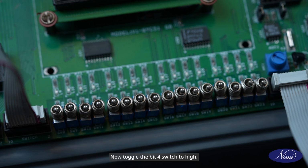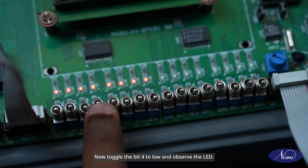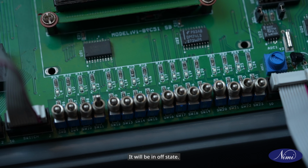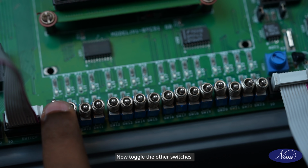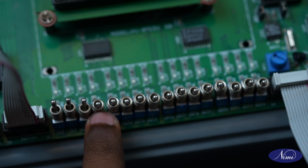Now toggle the bit 4 switch to high. See the LED. It will be blinking in the FF and 00 patterns. Now toggle the bit 4 to low and observe the LED. It will be in off state. Now toggle the other switches. There will be no change in the output LED's state.